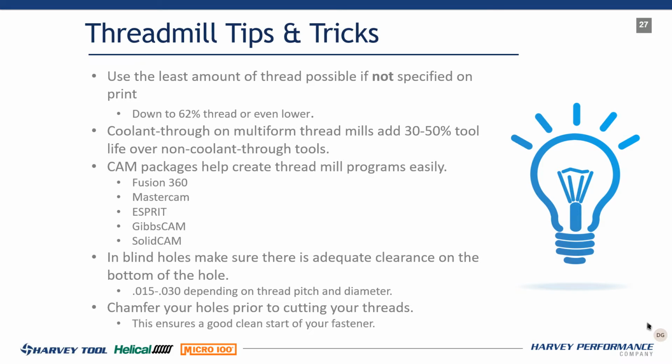There are several threading programs within your Fusion 360, your Mastercam, your Esprit, Gibbs CAM, SolidCAM. I don't want to discriminate. They're all great CAM packages. Get your hole, put it on your plot, create a thread mill program, put in your information. It will even let you break up those passes as well. Remember how I said 40, 30, 10?